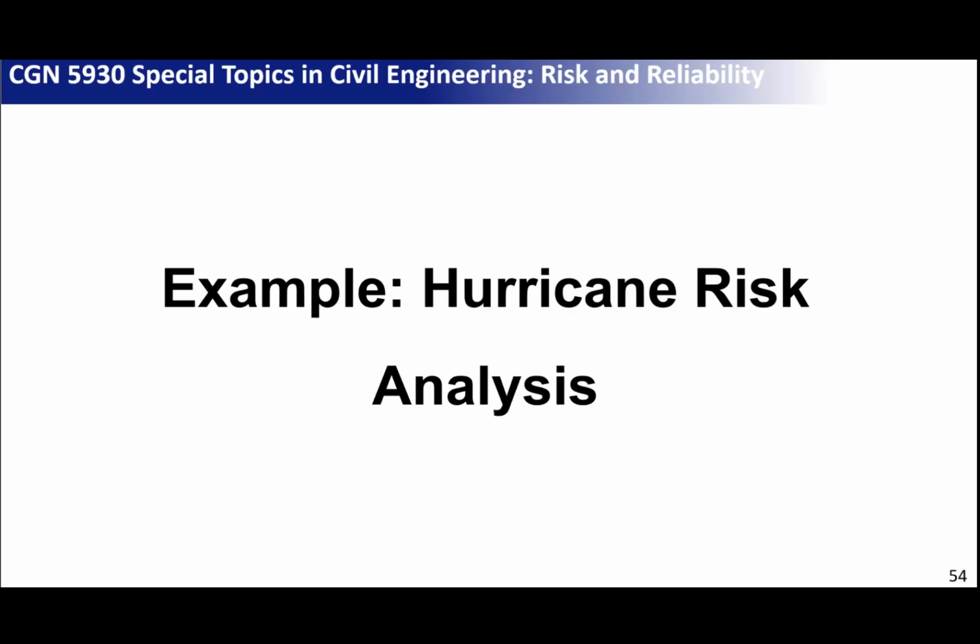And we measure them. Wind, we measure by wind speed. Surge, we measure by surge height. Waves, we measure by what is called significant wave height, okay? Or let's say wave height. What is the wave height? Significant wave height is the mean of the highest 1/3 of the waves. So it's kind of complex, but this is not the story here.